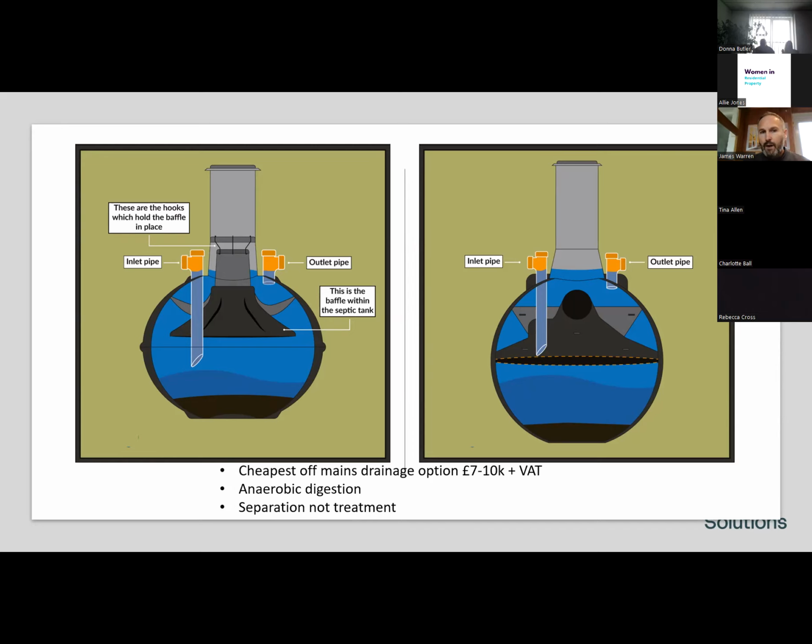And it allowed the same thing to happen, just separation. But instead of it being horizontal, left to right displacement for a septic tank, this is vertical. So if we look in the middle of that left-hand side illustration, you've got that sort of lampshade, that dark grey lampshade. That's called a baffle cone. That baffle cone stops the fat, oil and grease reaching the level of the outlet pipe and then going to the soakaway. What you can't see in that baffle cone is some tiny slots that allow the separated wastewater to get through, but nothing else.